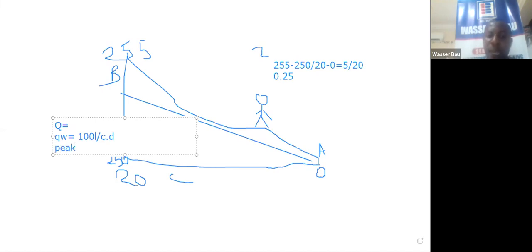For me, I normally use 2.2 as my hourly peak factor, but the hourly peak factor usually varies, by my DVR standard, between 1.3 and 2.5, depending on the population equivalent you are designing for. So you can choose any of these peak factors. Sometimes, in Abuja, when they designed Abuja, they used 2.3. They chose 2.3 to design Abuja for 1 million population equivalent.